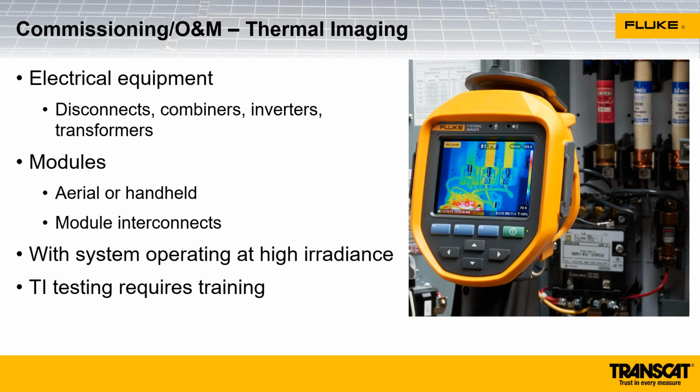When we're doing thermal imaging, we want to make sure that the system is operating at a relatively high level, and that's to make sure that the equipment is actually heating up a little bit so we can see that differential in temperature. Thermal imaging testing does require a bit of training to be able to do it well. There are some nuances to thermal imaging that require that training.